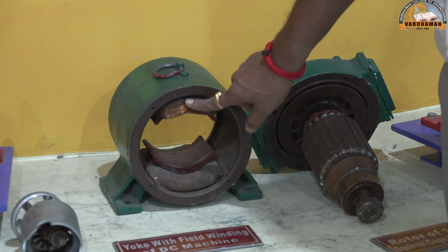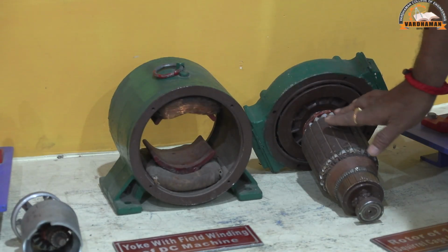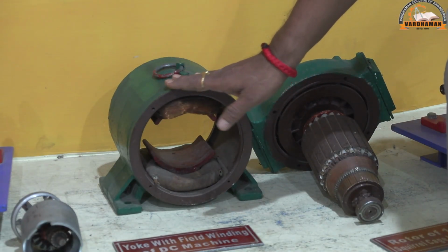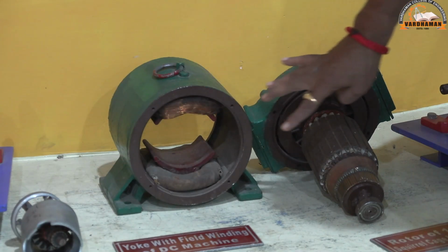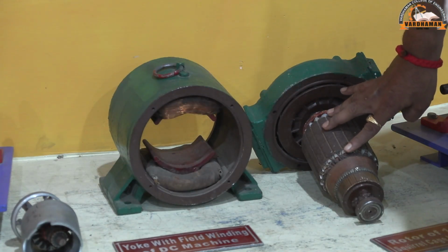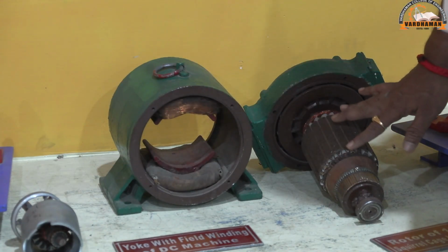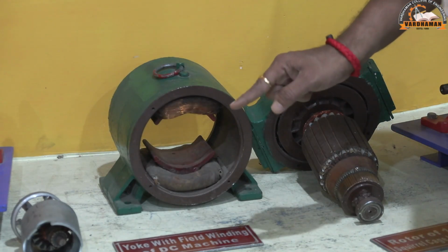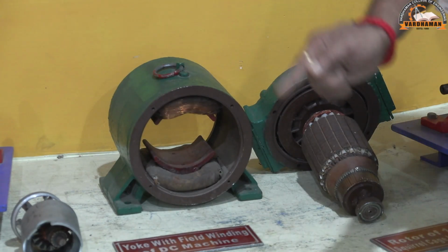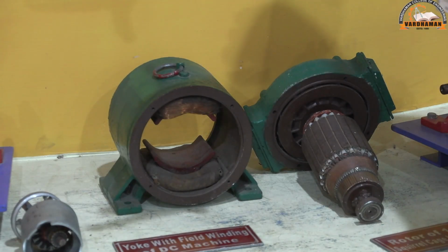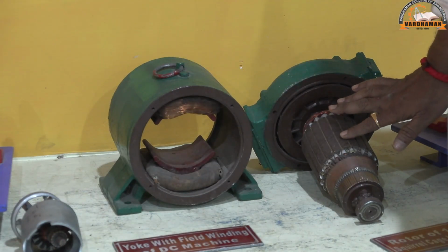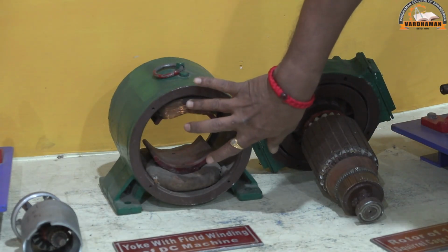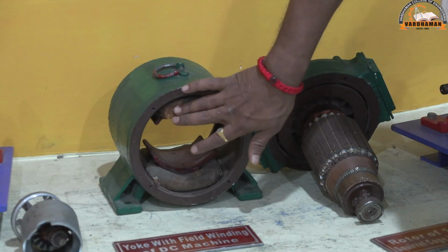Again, compound motors are connected as long shunt compound motor and short shunt compound motor. If the shunt field is connected across the armature as well as the series field, there will be a series field in series with the armature. There will be a shunt field parallelly with the armature and series field. So it is called long shunt. If the armature terminal is connected across only the shunt field, it is called short shunt.